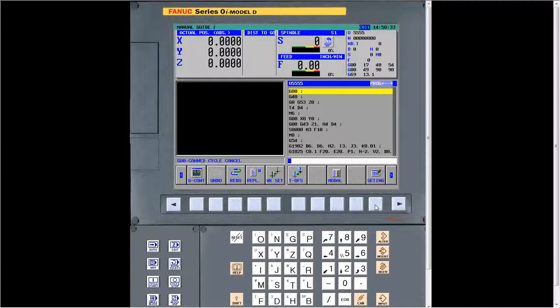Not necessarily how I want you to set it up, it's the way you want to. Within your fixture forms, what you can do, and I've had several people do this, they actually download their Renishaw probing cycles, so they're usually relatively short, and they put them in their fixture form. And then, when they're doing their programming, they'll just go grab one and insert it right into the conversational programming and use it right within Manual Guide i. Okay, so it is capable of doing that.